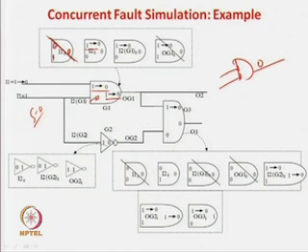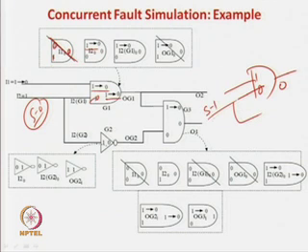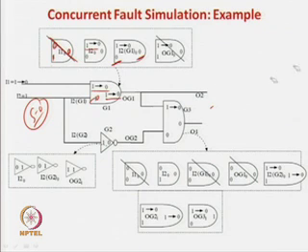When the input signal was 1 1, the gate with the stuck-at-0 fault looked like 1 0 and the answer is a 0. For the stuck-at-1 fault over here, you were applying a 1 over here, and now you apply a 0 over here. So this one will be changing from 0, the output there will be no change. So you need not compute this and you need not compute this. These values were retained the same as in the previous case when we applied 1 1 over here, and only small changes are this one.